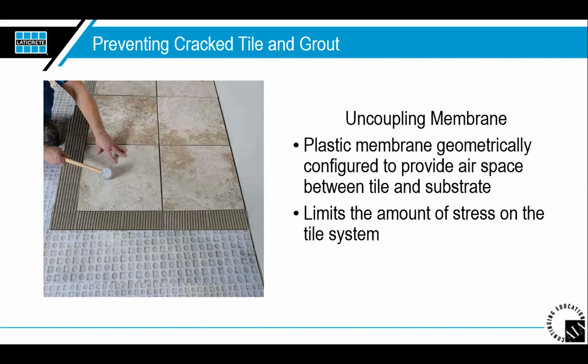These products usually have a sheathing on the back of them, like a fabric sheathing, in plane movement there, right? So, you know, I can't see my hands, but you've got the movement of left to right, right? So if a crack would occur, essentially if the crack was smaller than an eighth of an inch, the sheet membrane itself would span the crack. But even if the crack was so big that you actually do have a structural issue, that's not a manufacturer's issue or an installation issue, that's a substrate issue.